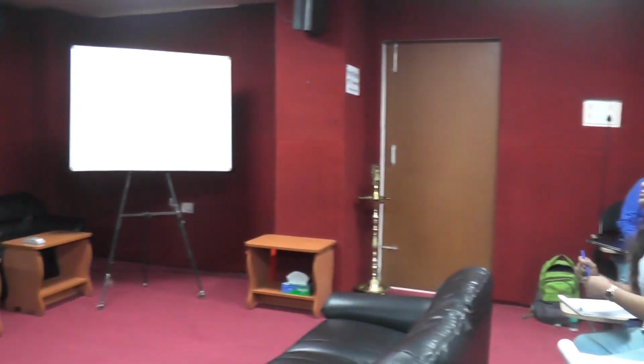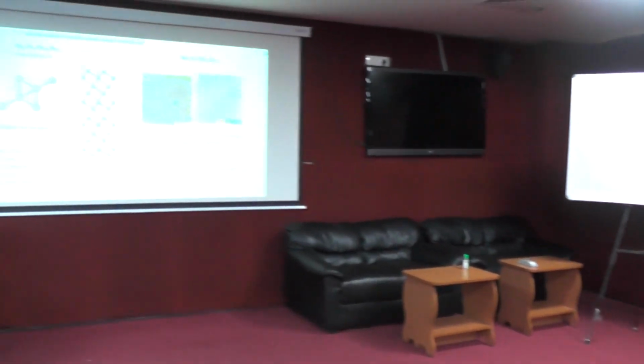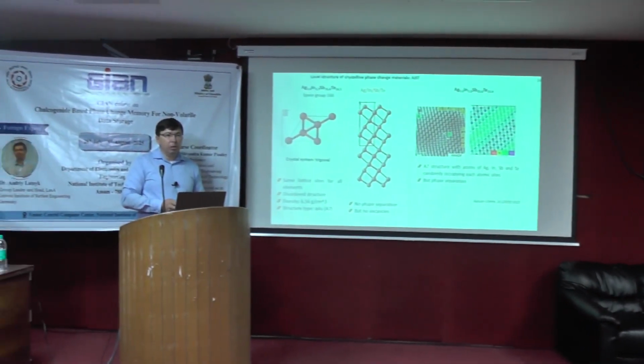Sir, good afternoon. Sir, I have a doubt regarding AIST: we saw that antimony is segregating by itself. So is it possible that we can confirm from an XRD, X-ray diffraction pattern, that Sb is getting segregated like that? If there is enough material, I think yes, you can see some precipitates in the structure. Okay. For my sample, I am getting tellurium segregated kind of thing.